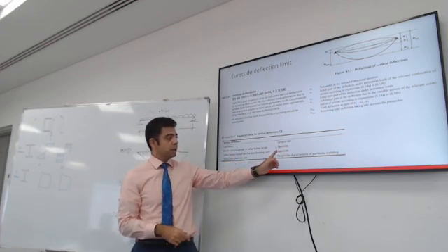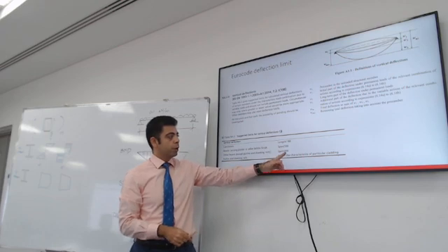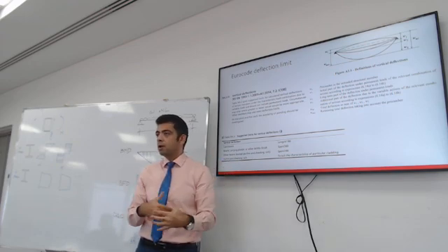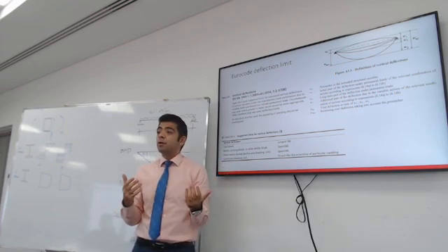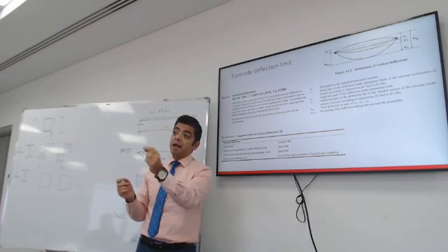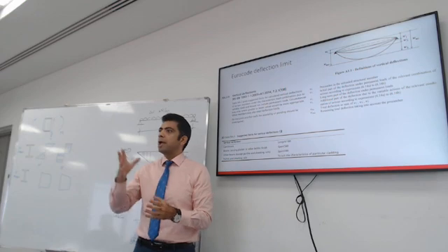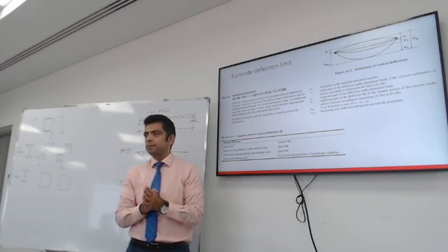So I would follow the recommendations. If it's a generic beam, it would be the span divided by 200, unless I tell you otherwise. I could say the maximum deflection you should check for is the span divided by 300. Then you would use that recommendation. All right?